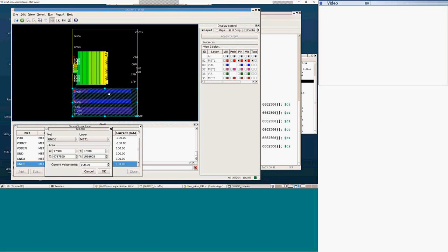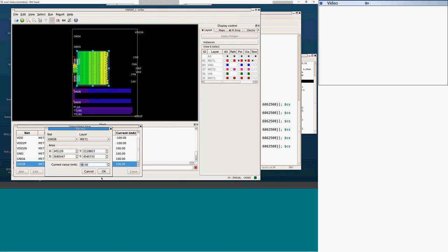It doesn't do anything, it's an open metal. So should it be here? Yes, it's here. So how much current would you expect to be consumed in this area? At full load, I would expect around 50 milliamps. So we say that in this area we would expect 50 milliamps flowing down from top metal to metal 1. Okay.